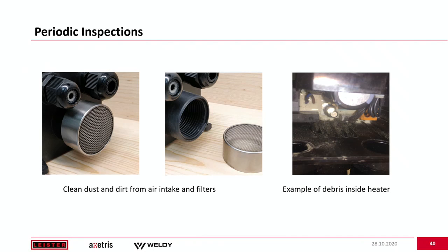Well, what's going to happen is over time, as that dust starts to build up, you could potentially have issues with the blower and potentially failure. Or you could potentially have all that dust and debris actually being blown into your process. All of those are undesired effects. So let's make sure that we take the time to clean our heaters to make sure that we can run our equipment properly, but more importantly, that you produce a quality product at the end of the day.